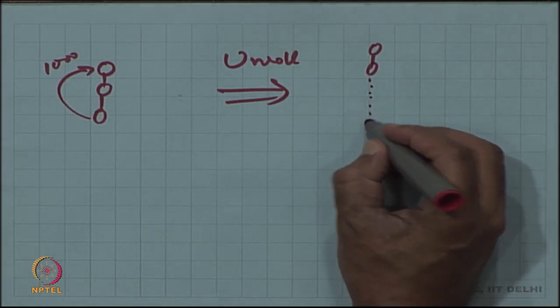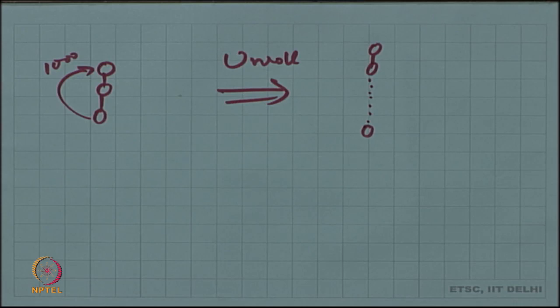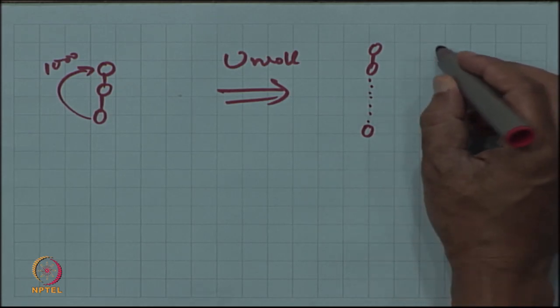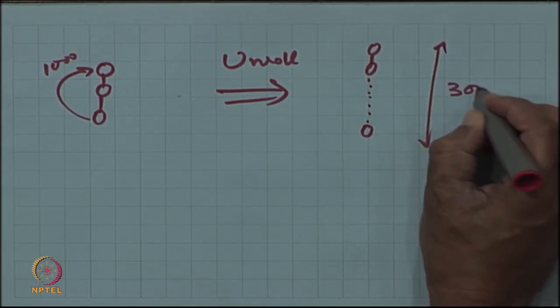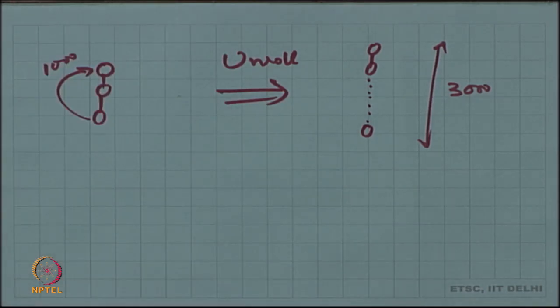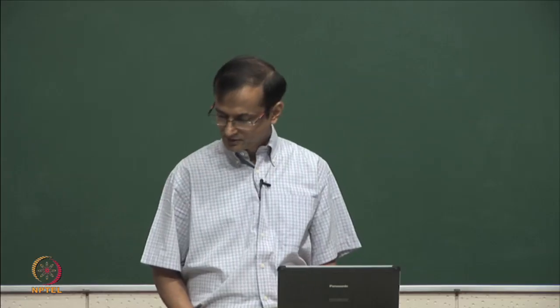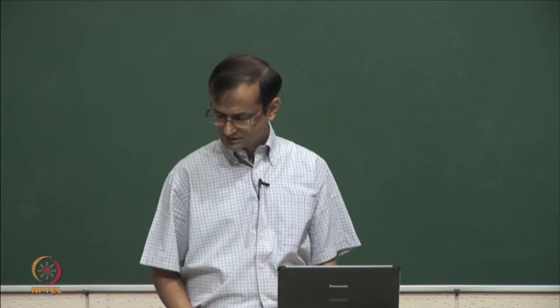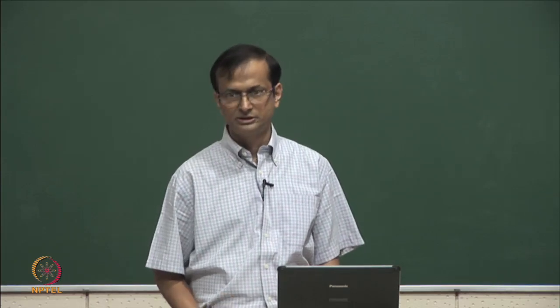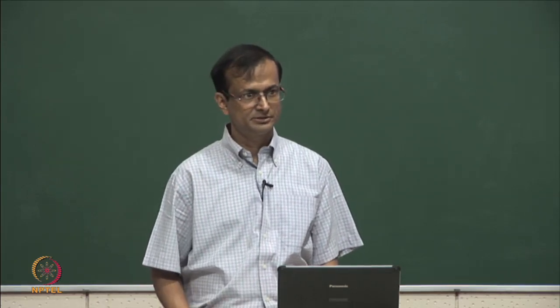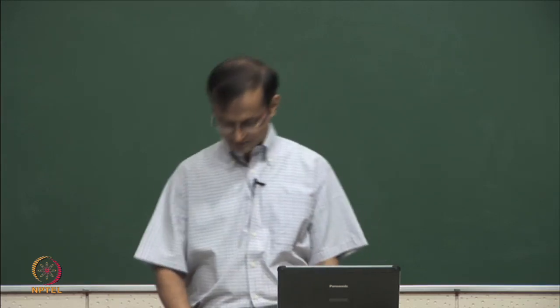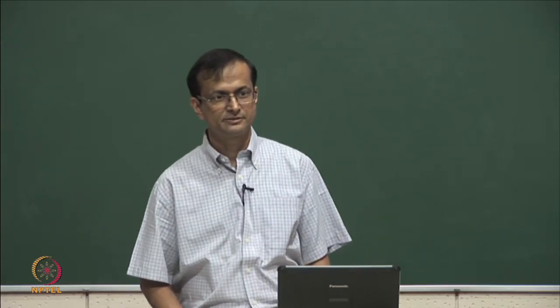That is what it becomes. This is the equivalent of our other argument that there are 3000 instructions when you do it in the processor. Here, the equivalent of an instruction is what happens in each state, right. So, you actually have a very large number of instructions, maybe by default it is 3000 cycles as you just expand the original loop. What kind of implication does it have on the quality of the FSM that is generated? An FSM that has 3 states versus an FSM that has 3000 states.